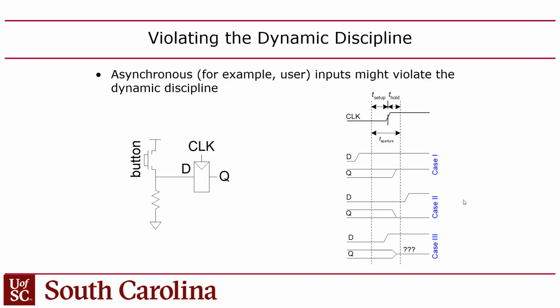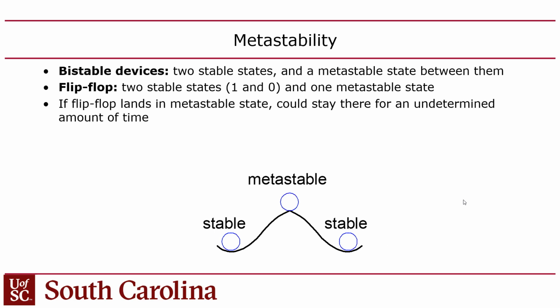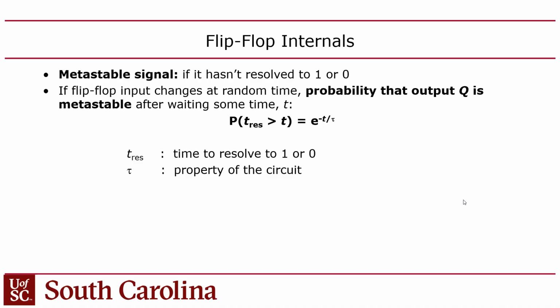Also, if you know about SPI and UART and I2C, and all the communication protocols that are used for chips to talk to one another on a circuit board, all of which could violate that dynamic discipline, and there's nothing you can do about it. And there's no technological way to design this flip-flop that makes it immune to metastability. Okay? So what do we do? That's just a depiction of metastability. Okay, so